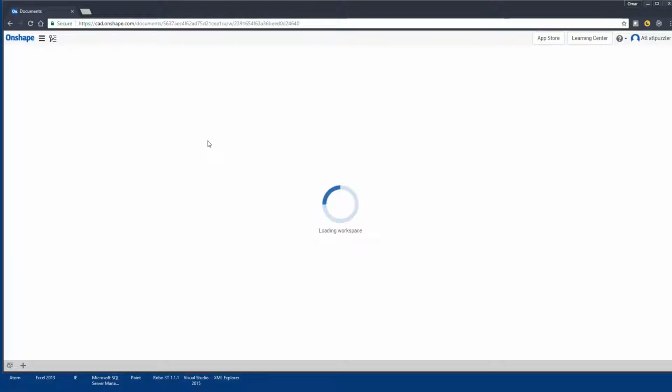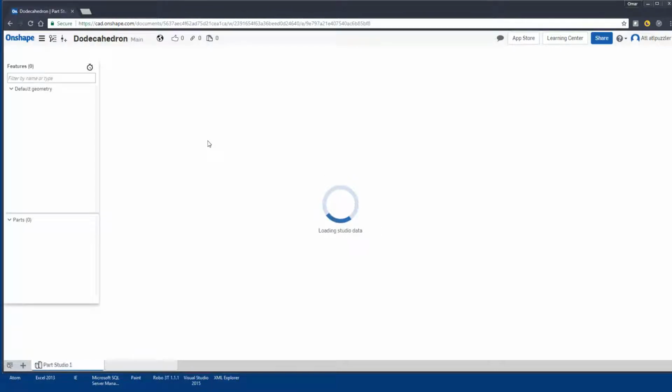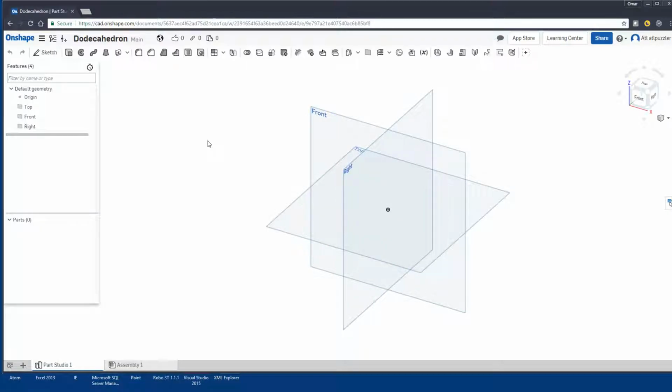The reason why I called the document this is I want to go with you guys over how to create a solid called a dodecahedron, which is something that will be useful in the future, not just for a Megaminx. So once we create it, we'll version the document and publish it and put it somewhere so that you can have it in your stash and reuse it in the future. You can make your own, you can use mine, or by the way, you can just use someone else's. I'm sure there are hundreds of them in Onshape.